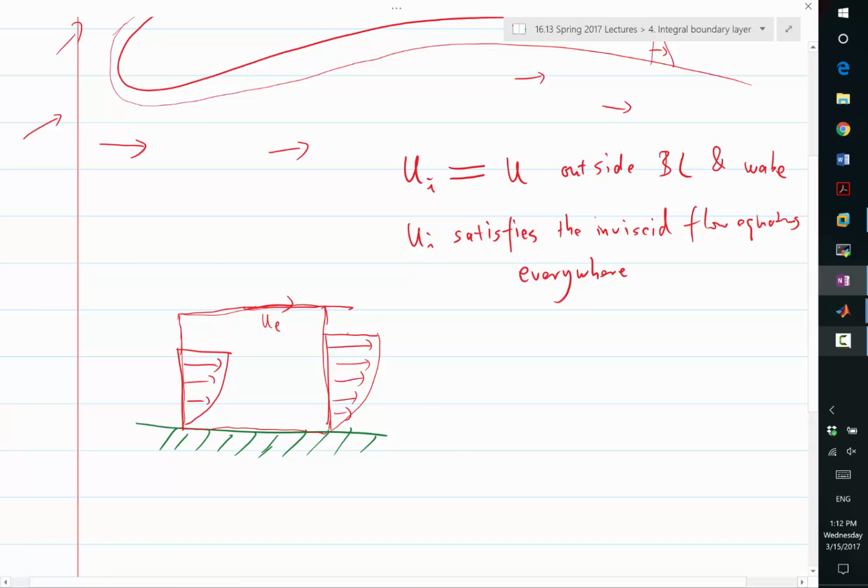We have two similar velocity profiles, but if you extend it up further, you can see the boundary layer at the left contains more mass flux than the boundary layer at the right. The boundary layer has grown, and the defect has also grown, because the boundary layer profile is similar.